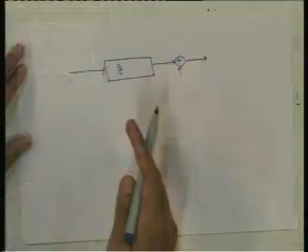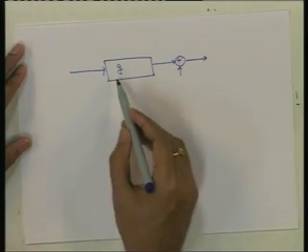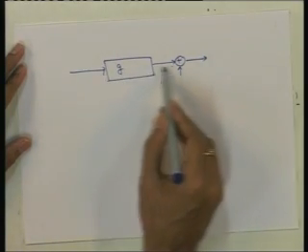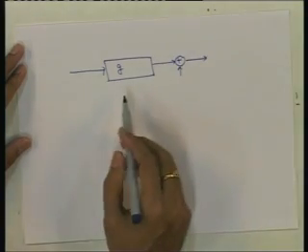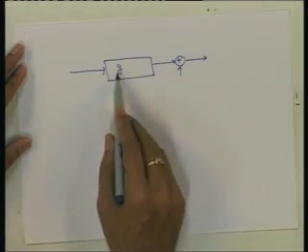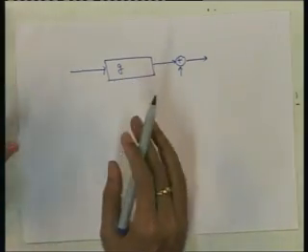But in the channels we have discussed in this class, we have not considered any G. That means it is directly being just added by a noise. In general, channels can go through some function, and the simplest functions that we consider are the linear filter channels.